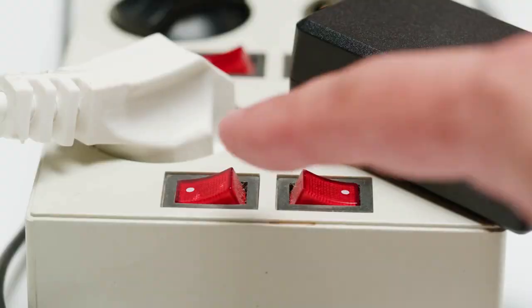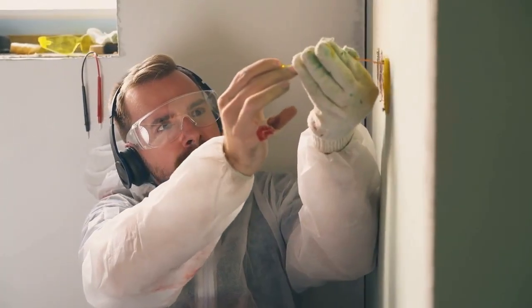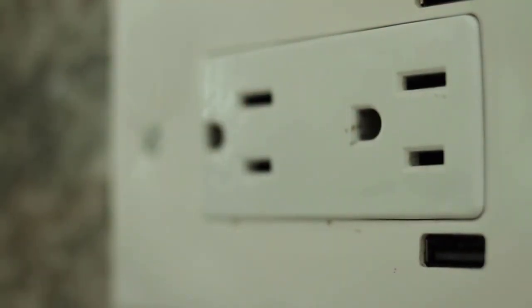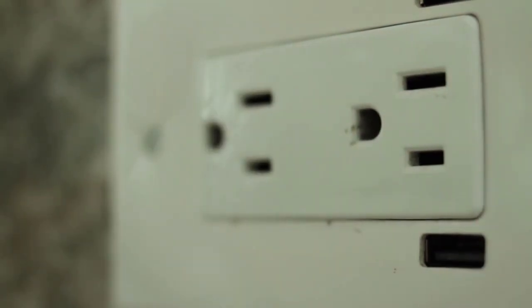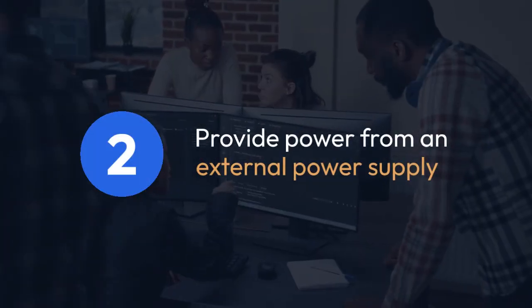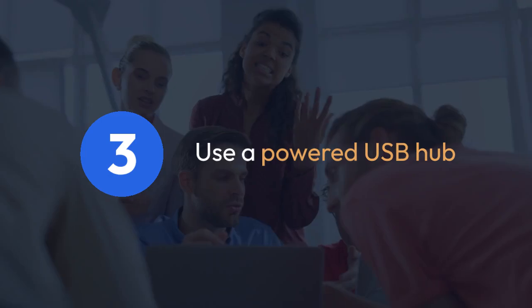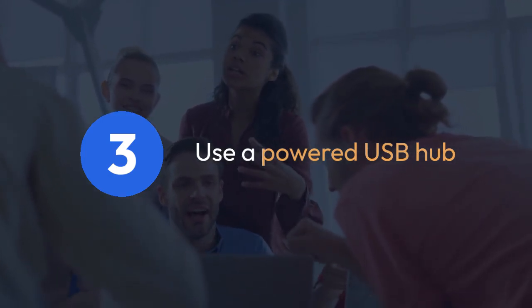4. Power issues are another potential culprit. Sometimes, insufficient power prevents the USB interface from functioning correctly. Your STM32 may require external power, especially if the USB port isn't providing enough current to both power the microcontroller and drive the USB communication. Check if your board has an external power connector, and if so, provide power from an external power supply. Also consider using a powered USB hub, as some computer USB ports might deliver insufficient current.